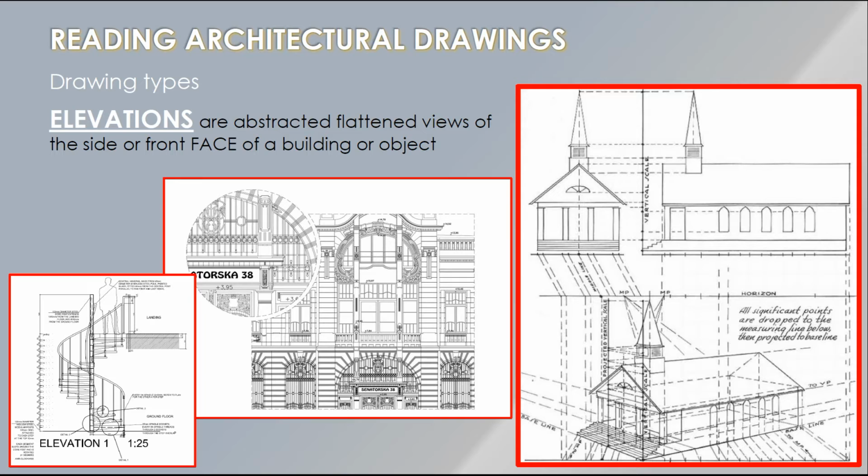In the lower left, a similar example. Just by looking at this, you know that this is a spiral stair going to a landing on a mezzanine on a second floor, but that's obviously not what a spiral stair looks like. This is drawn for the most part to show how far vertically each step is from the next step, and along the left edge of that detail you can see that there's a clear dimension string identifying the thickness of each step and then the distance between each step.